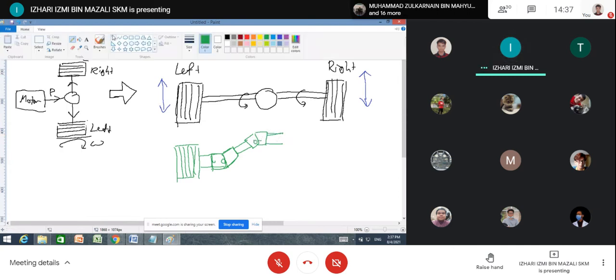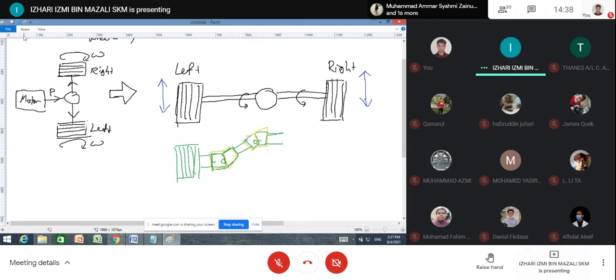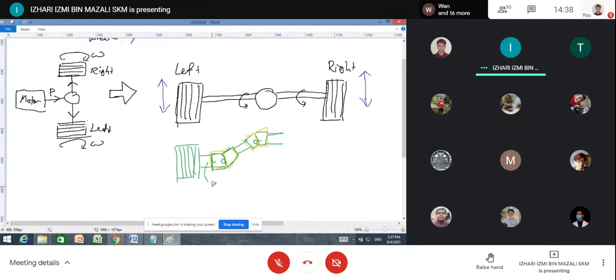So you will need to use at least two universal joints: number one, number two. And then here you have a straight shaft, and here a straight shaft, one component here and one component here. And from here only you go to this one.